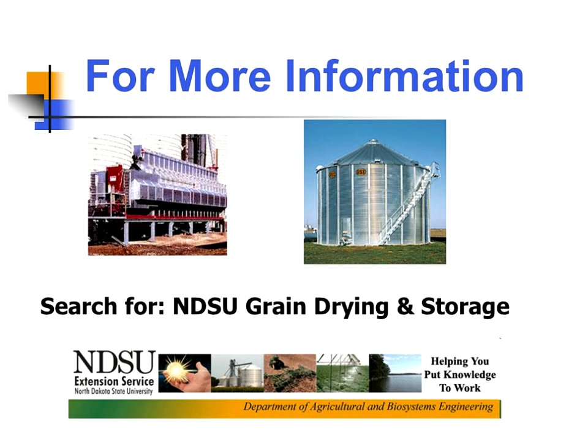As we get later into the fall and we're looking at cooler temperatures, we're looking at a little bit higher humidity. When we're talking natural air, low temperature drying, the primary thing is the outside temperature. Humidity has a little bit of effect as far as the final moisture content, but not a whole lot.